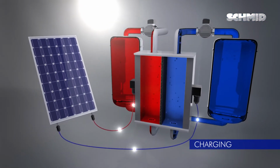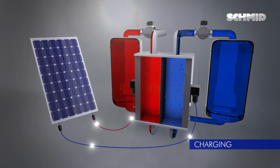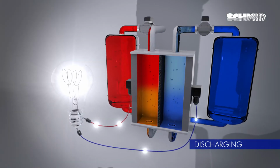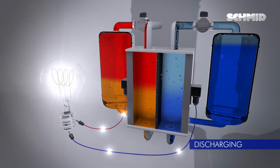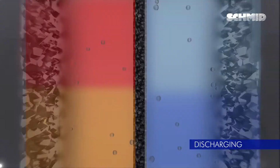Once the grid cannot provide energy to the battery system, the vanadium redox flow battery swaps to discharge. Vanadium-5 and vanadium-2 ions carry the chemical energy into the cell stack. The chemical energy stored within the two electrolytes is converted to electrical energy, feeding the external load.